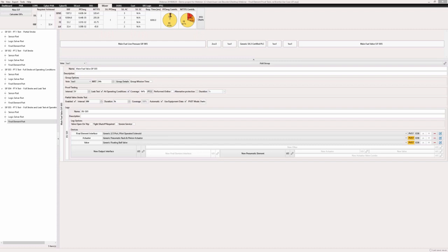One of the things that a user could do is simply look, if they have a safety PLC, the application program typically has some kind of identifier, maybe a CRC code. They could just see, what is that CRC code? Is it the same as at the end of commissioning and installation, when we started to introduce the system? Is it the same at this point when we do the proof test? If it is the same, then your application code hasn't changed. And you could limit yourself to looking for dangerous and undetected failures in the logic solver, and you can separate them. You don't have to do complete loop-to-loop tests.